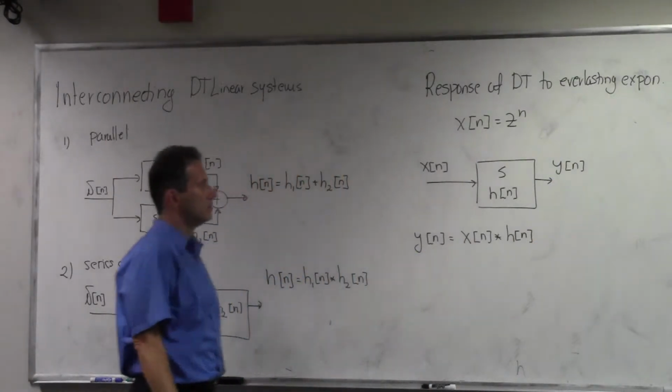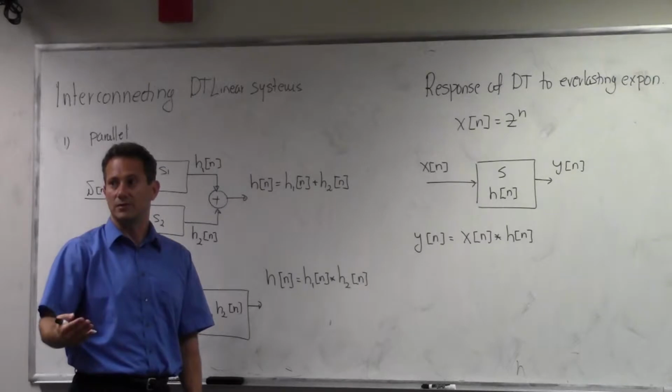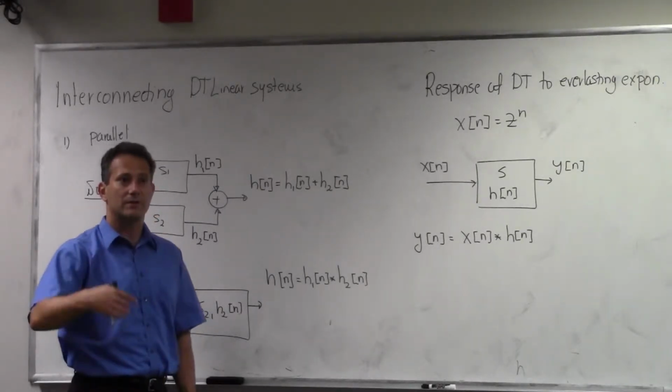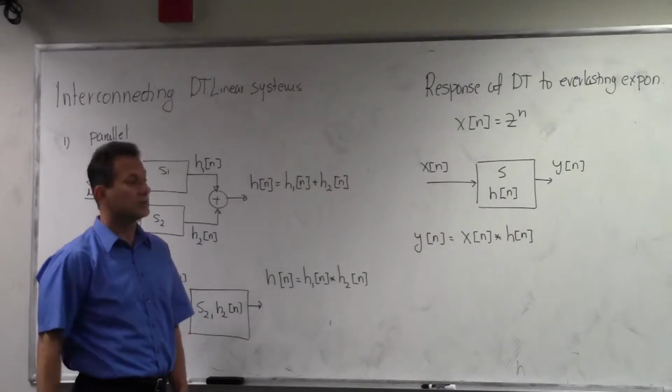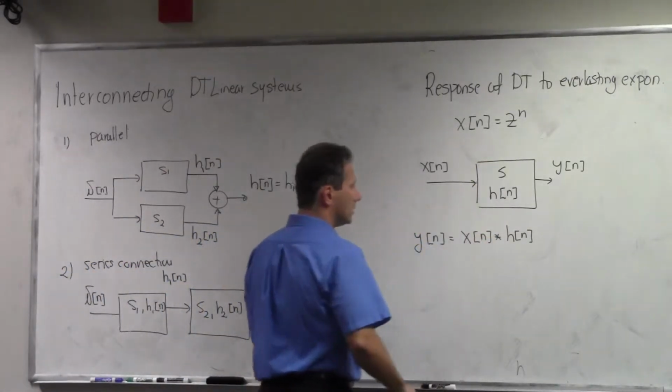Right? That's our general understanding for a zero state output. If you have zero state output, then your output is a convolution of whatever comes as an input with the impulse response of the system.